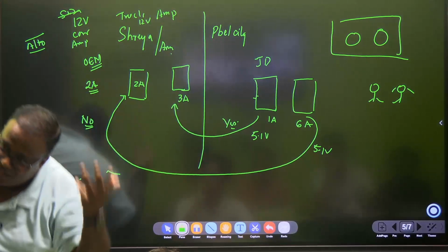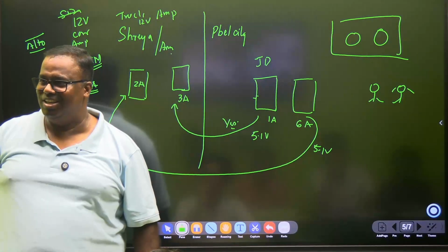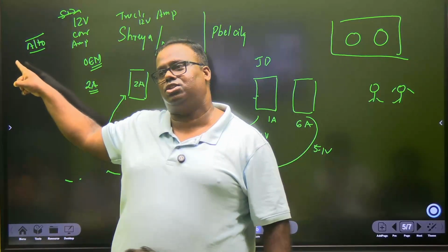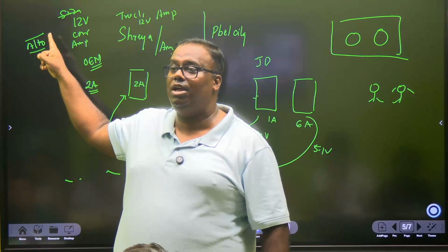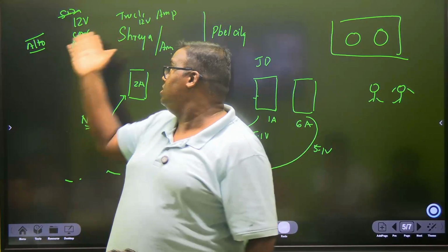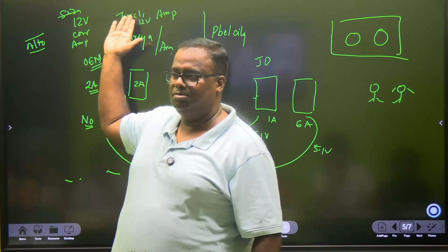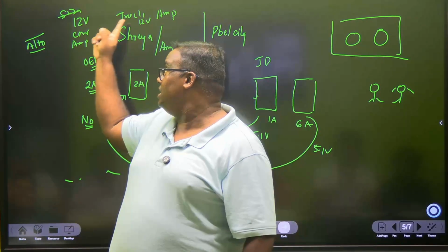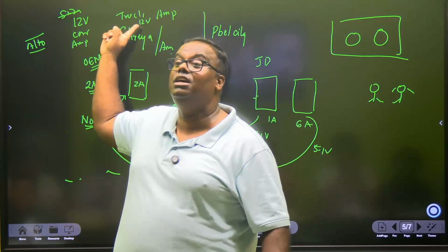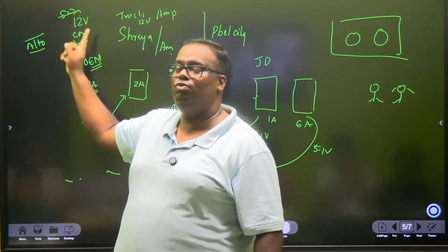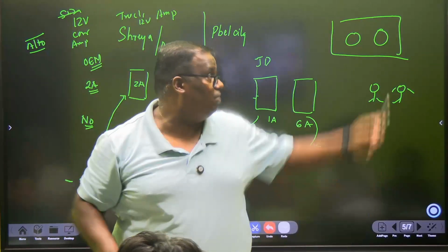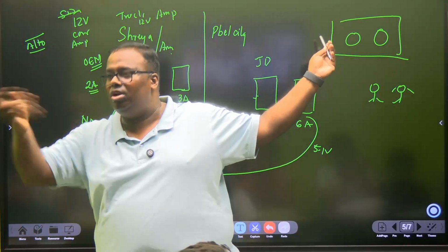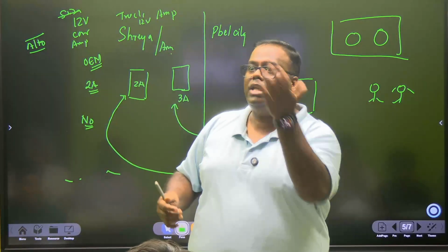The Santro will drain off in 1 minute. Did you understand? The Santro's capacity is less. But if it was the other way around, can the XUV jump the Santro? Yes. The XUV should be jumped by a similar vehicle, Scorpio N, or with a truck. Mother to baby, not baby to mother, both are 12 volts. But the current capacity of this one is higher. This is a langar and these are 2 babies. And if you do the other way, you are trying to feed 14 children with my mother. My mother's quality is good, but her withdrawal rate is not high, and you want, auntie, roti.